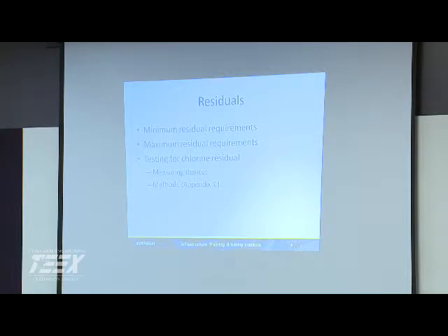And I think a lot of systems use it out on the distribution side for whenever they're using 10 or 15 or 25 parts per billion or even higher, because that way you can tell more easily. So I think there is one test strip that is EPA approved. A lot of times they go down to the pool supply and pick something up and that's lacking, but it's interesting if they're able to utilize that, because otherwise you gotta know how to do dilutions and then calculate it back out if you're running a real high residual or something.